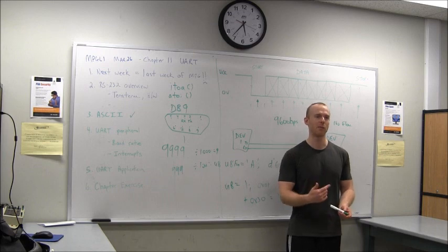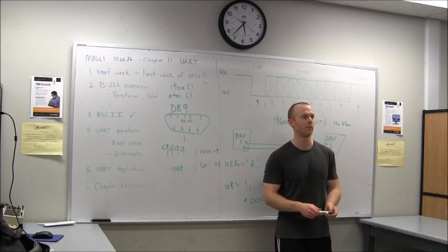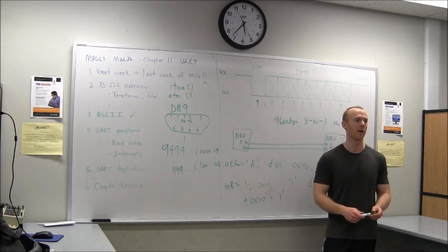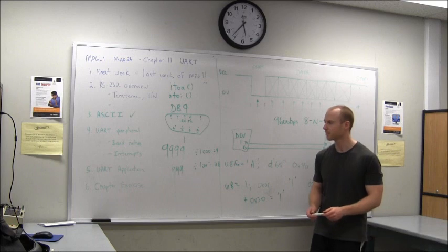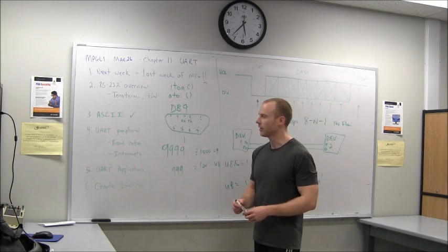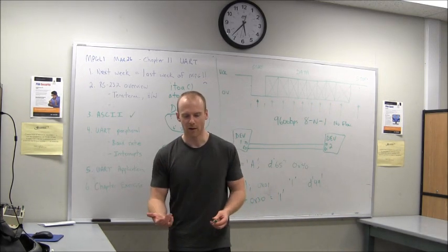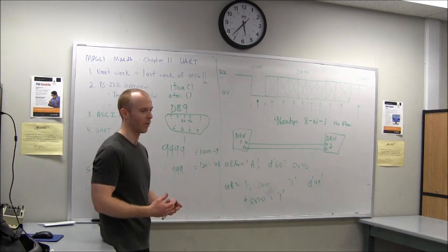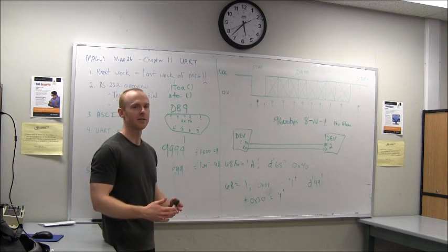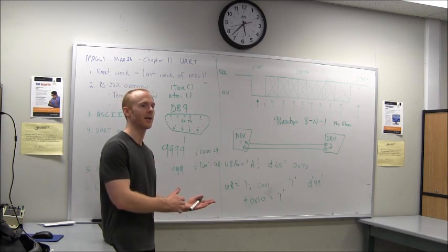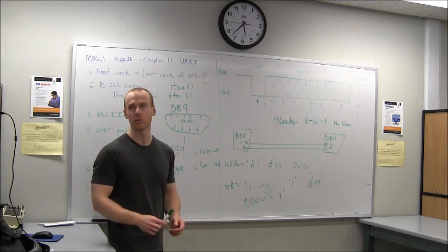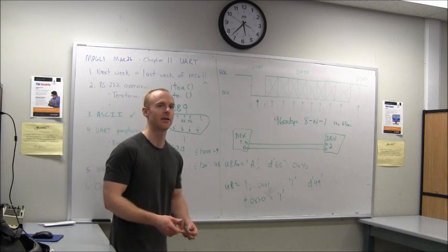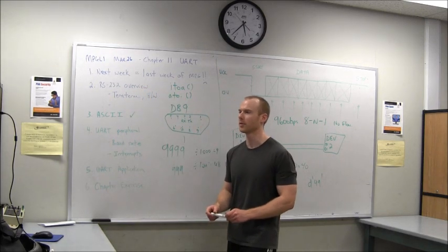We're always going to, as soon as we get a byte from the computer, use our interrupt to go grab that and throw it into our receive buffer for our UART peripheral, and then we'll decide what to do with it. The application itself, we want to set up to be able to receive data coming in, but also give us a mechanism where we can just send out ASCII strings to a function, and then the UART application will take care of sending those to, right now, the terminal, and we'll probably make it point somewhere else, like the LCD later on, or do something very similar.